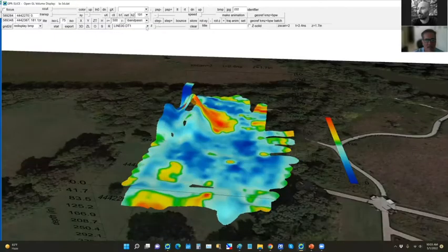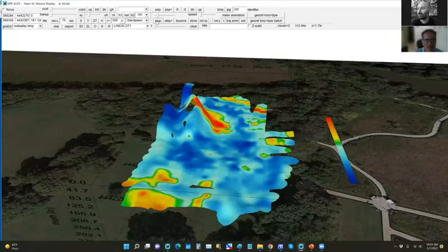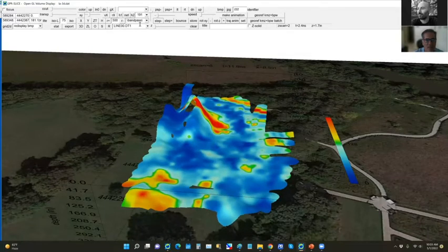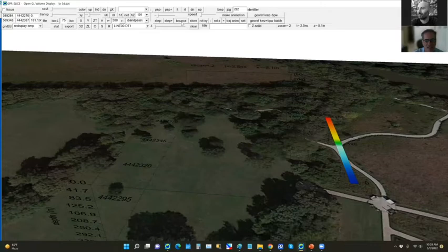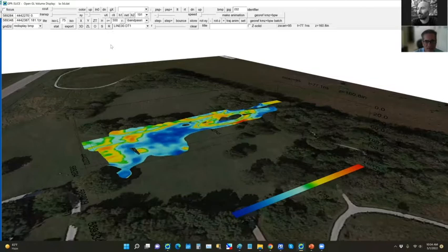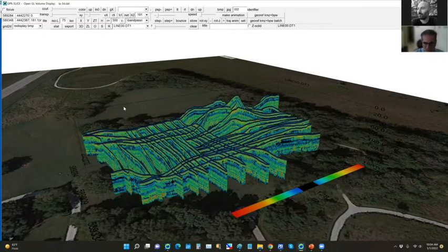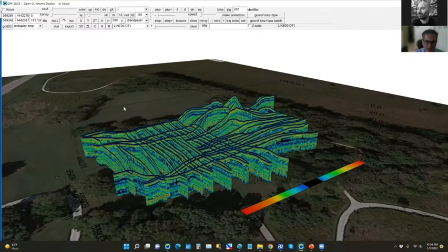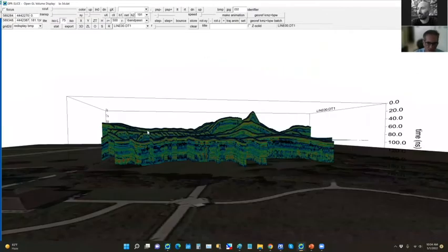And again, the ZT are the topographic slices. We can actually put on the ZL, which are the level plane slices. These aren't quite as interesting, but it's slicing through the topography. And you can also put on the topographically corrected radar graph. Now, this particular site, this is like a 23,000 scan profile with only about 200 samples in the depth. So that's good enough to get an OpenGL. But if you had a 100,000 scan profile that was digitized at 1024, it probably wouldn't render completely.